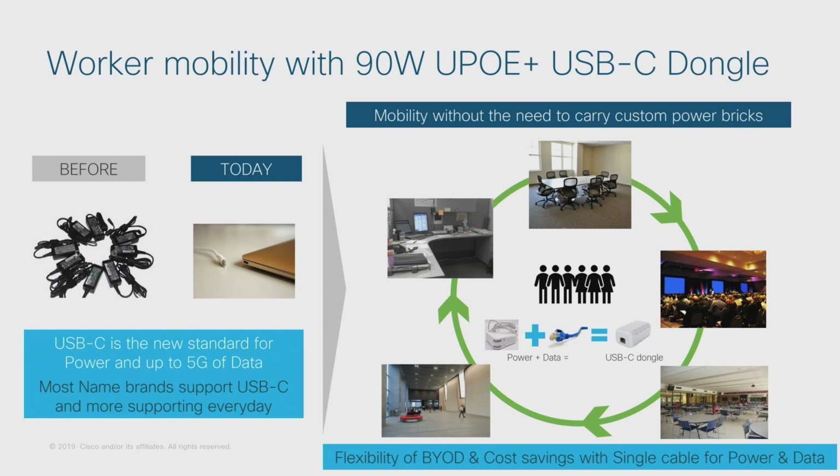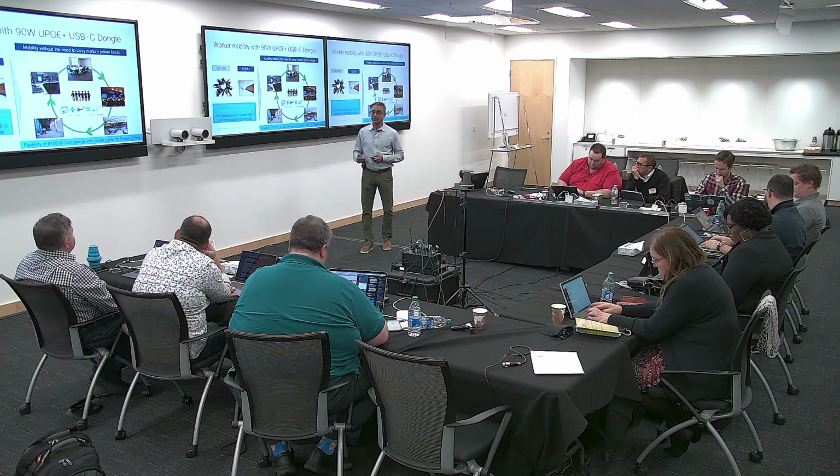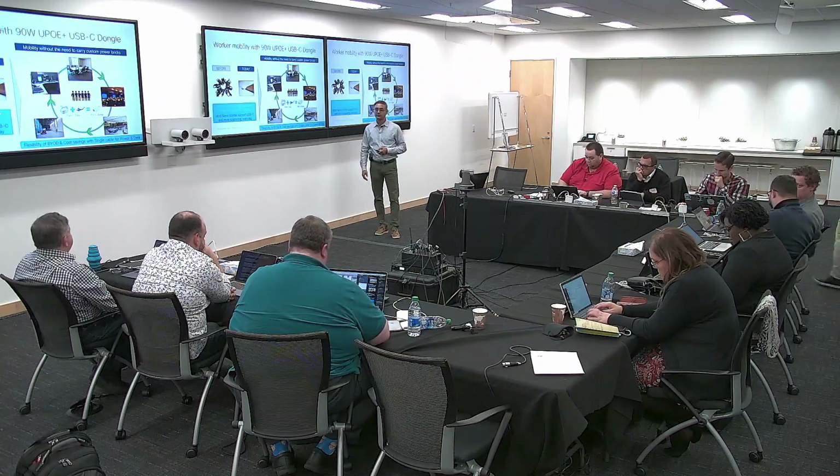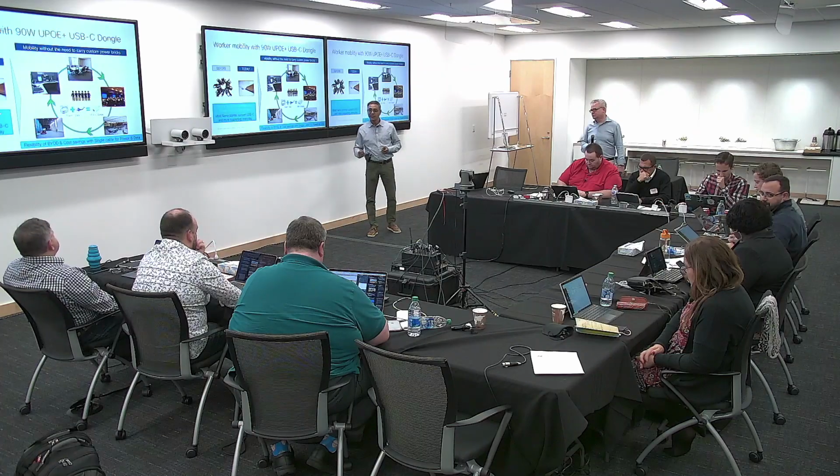So you're pushing 90 watts out of a PoE port, typical laptop, 60 watts. That's right, 60 watt charger. So even a bigger one, like a MacBook Pro type thing, which is pulling what, 70 watts, 75 watt chargers? 75 watts. Yeah. So that would be a class 8 device, which would get about 75 watts of power. So you can pretty much power any sort of modern laptop. Laptops, tablets, smartphones. And essentially, the cost saving is significantly high. You don't have to have so many AC outlets out there in those tiny conference rooms.